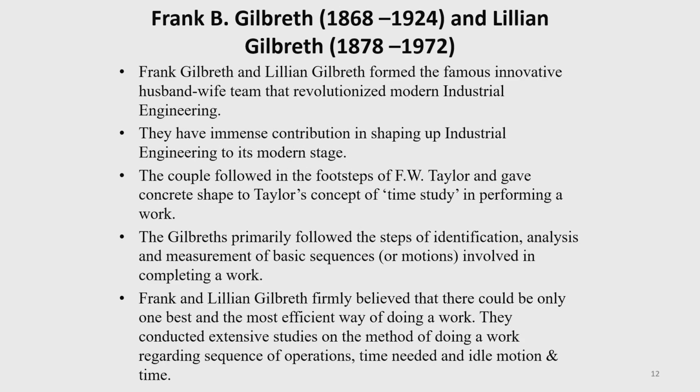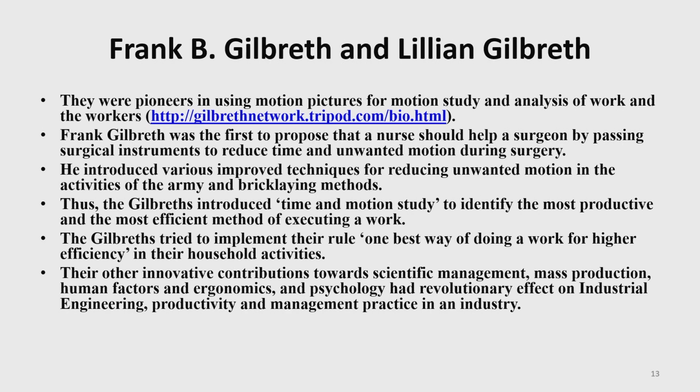So the Gilbreths primarily followed the steps of identification, analysis and measurement of basic sequences or motions involved in completing a work. So they analyzed each and every motion. Frank and Lillian Gilbreth firmly believed that there could be only one best and most efficient way of doing the work. They conducted extensive studies on the method of doing a work regarding sequence of operations, time needed and idle motion and time. In fact, they applied these methods in their home also to do work in the optimum way. So they were pioneers in using motion pictures for motion study and analysis of work and the workers.